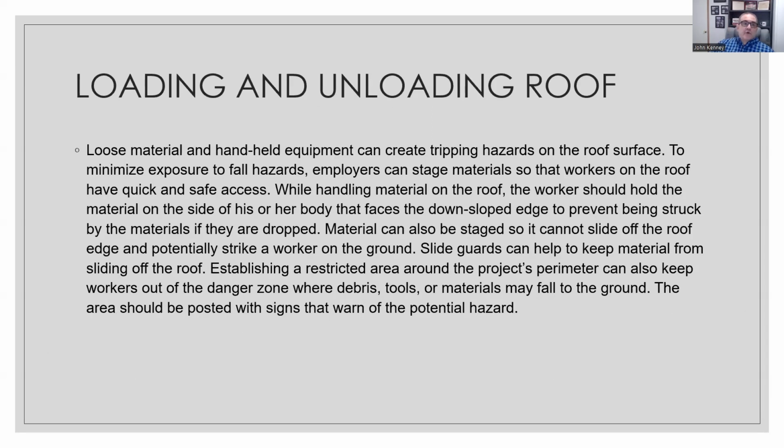Loading and unloading a roof. Loose material and handheld equipment can create tripping hazards on the roof surface. To minimize exposure to fall hazards, you as the employer can stage material so the workers on the roof have quick and safe access. So it goes back to other things besides safety when we talk about processes in place for efficient and safe operations. You want to have a load plan in place. This will eliminate a lot of the hazards that you're going to come up against.